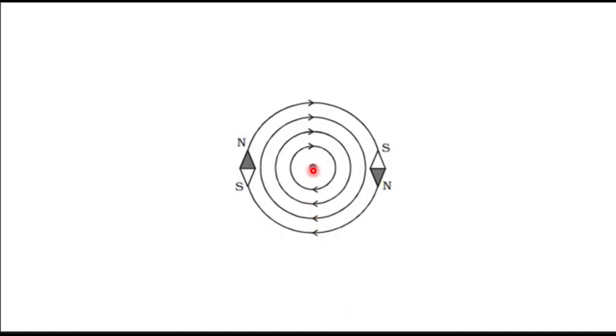Looking at a conductor head on like this, where the dot is the conductor passing current through, we see that these rings of flux develop around it. And we also see that over here those rings of flux are going downward, over here those rings of flux are going upward, and because of that, this half is opposite this half in magnetic polarity, as you can see here.